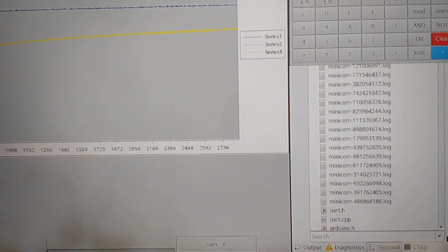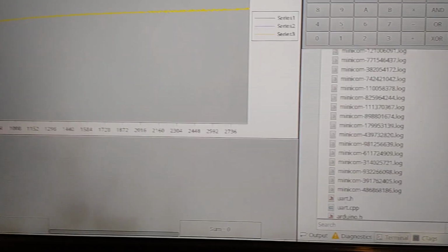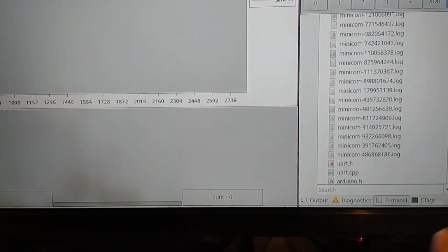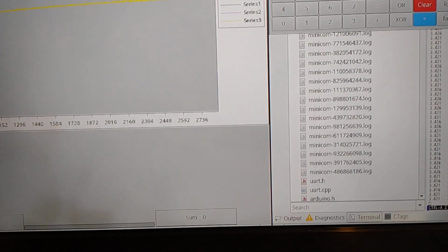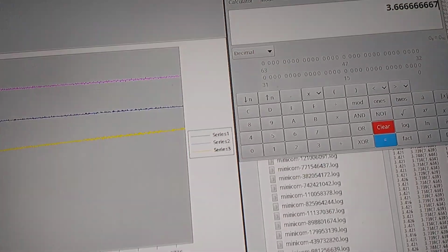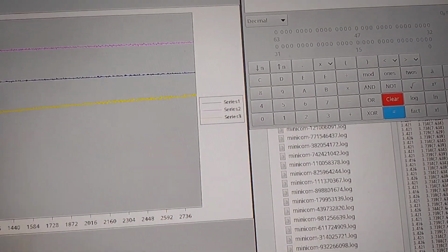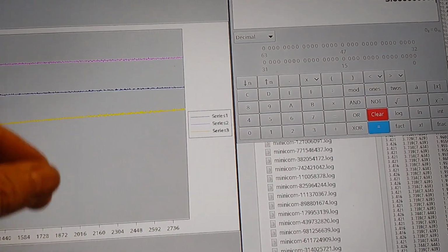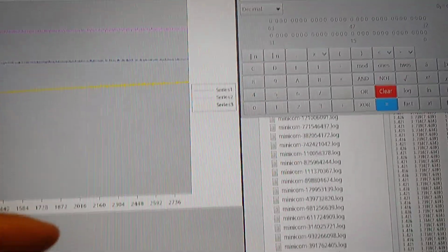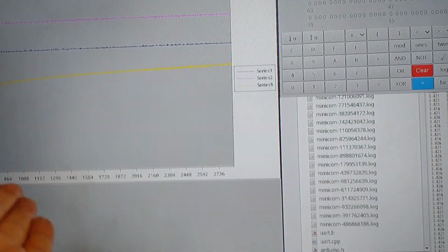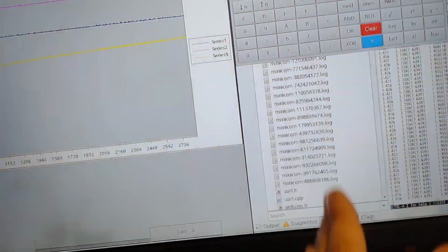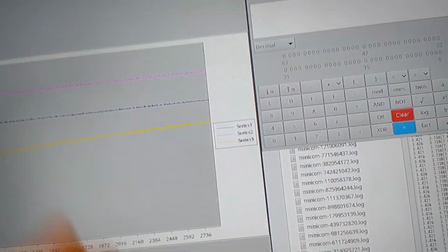But what you can do is you just focus on one cell at a time, and go round until you've ended up with them all at the same voltage. That's how it will work. Battery to cell sort of thing. And I would say stay on the same cell until that cell reaches the average, and then switch to another. And you basically keep going around this.